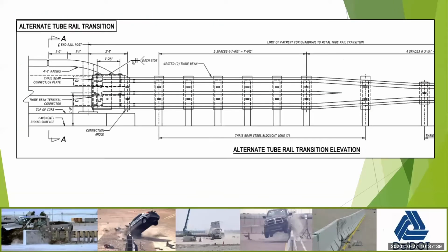And so those that remember the Craig Stevens rail and the 3-tube rail, we have also adopted a transition that's in the bridge design manual for that application as well. This is originally an Alaska DOT tested rail, or a transition for tube rails, and we've adopted that and modified it for the DelDOT 3-strand tube rail. There's also the option to use the concrete end post for that. We adopted this to help with accelerated bridge construction, so as to avoid slowing down to cast that end post.